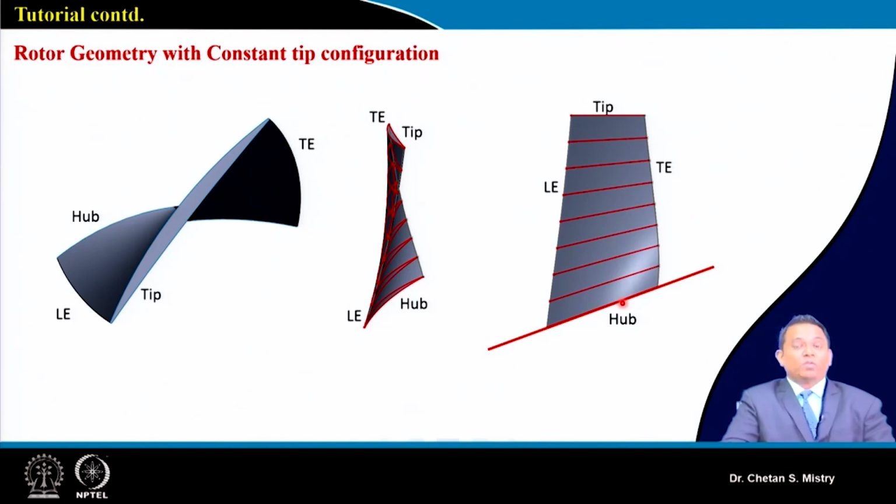Okay, so this is very important when we are discussing a transonic compressor. For a subsonic compressor, there is no problem. Straightaway, all the cascade data that is available with you, you can use. And that's the reason why most of the time when we are doing our design for a transonic stage, we are making use of computational tools only. Okay, so most of the designers, most of the engine design companies, take help of their own code for doing the simulation, or maybe they are using commercial tools which are available.